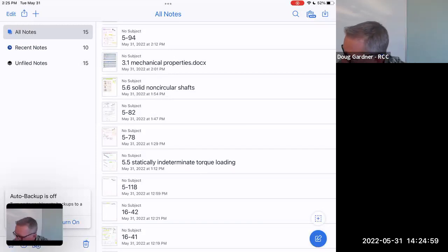In an I-beam, this distance from here to there is really far. That upper member, when you put it under pressure from the top, is going to want to compress a lot, way up there, whereas the middle stuff, I talked about this in chapter 6, doesn't change length at all. The bottom ones are going to have to pull way apart, and they're not going to want to do that. So you want all your material far away.